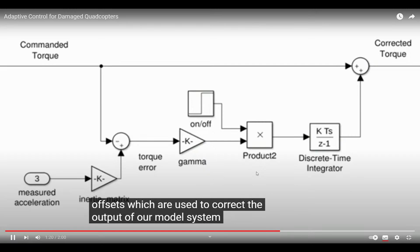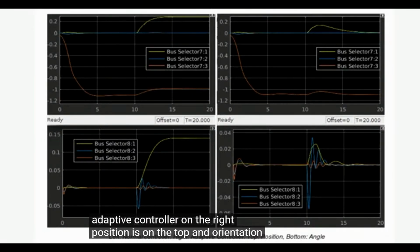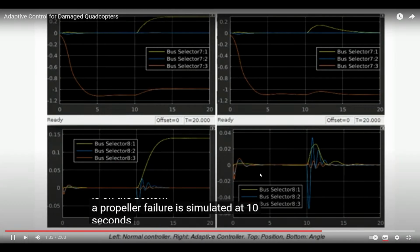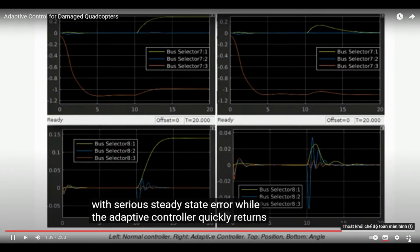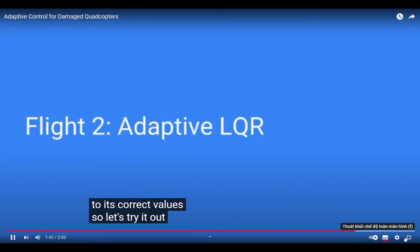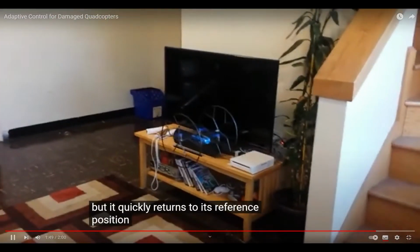In simulation, we compare the standard LQR controller on the left to our adaptive controller on the right. Position is on the top and orientation is on the bottom. A propeller failure is simulated at 10 seconds. Notice that the standard controller ends with serious steady-state error, while the adaptive controller quickly returns to its correct values. So, let's try it out. As you will see, the drone moves slightly to the side when the error is introduced, but it quickly returns to its reference position.